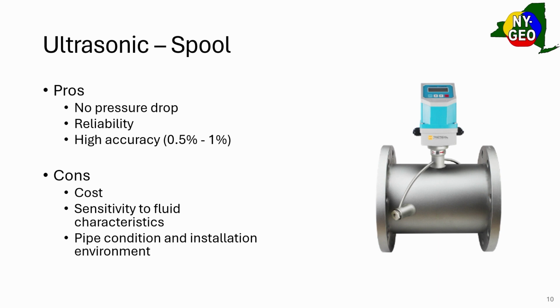But if you're trying to measure chilled water, be careful cutting open insulation on chilled water pipes to clamp on a meter, because you can end up rusting the pipe and fouling up the sensors. So pay attention to the conditions of the fluid which you're trying to measure, because interrupting a continuous insulation on something that will condense can cause some real problems later.